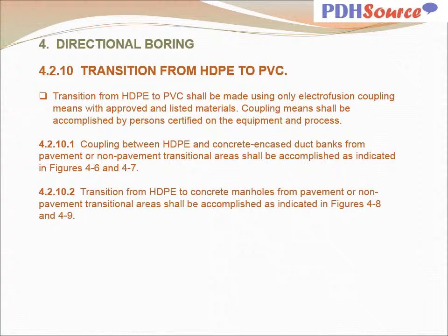Coupling between HDPE and concrete encased duct banks from pavement or non-pavement transitional areas shall be accomplished as indicated in figures 4.6 and 4.7. Transition from HDPE to concrete manholes from pavement or non-pavement transitional areas shall be accomplished as indicated in figures 4.8 and 4.9.